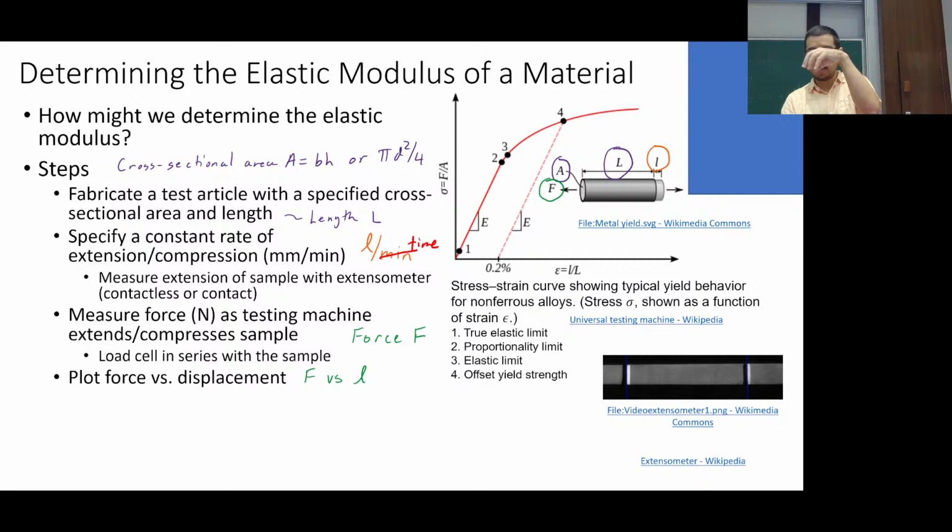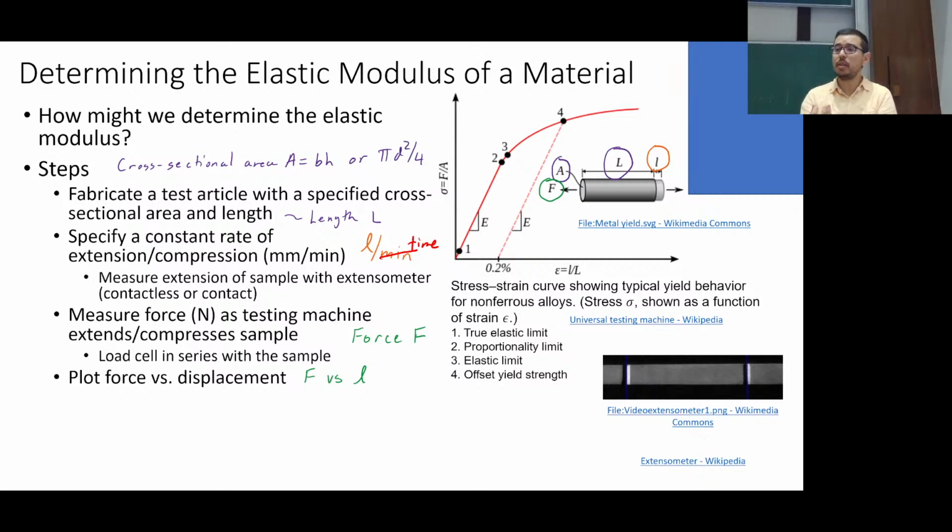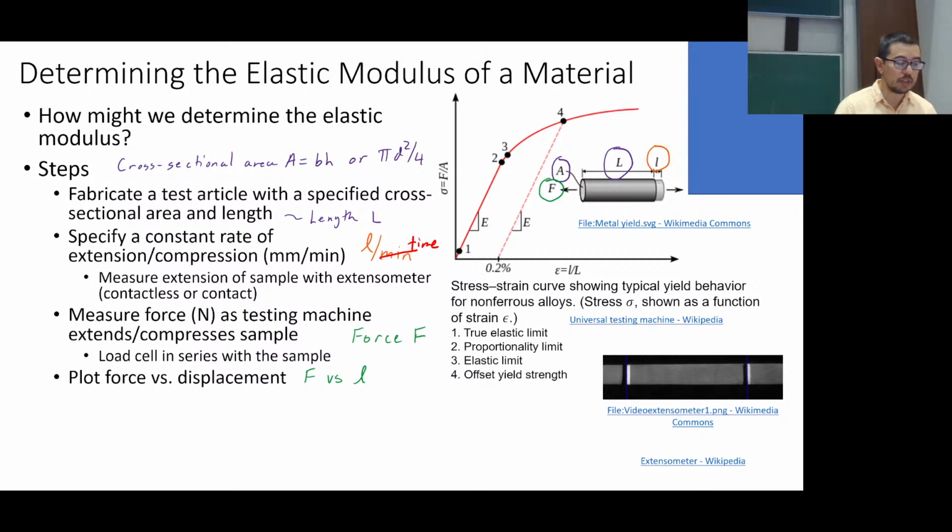So there's a head that's going to be moving, and then there's a base. Knowing that it has some gear ratios, it probably has an optical encoder somewhere in there. I don't know exactly how they're doing it. But we're just using the displacement of the head relative to the bottom, and that seems to give us good enough results. And then there's a load cell. The load cell is sitting on the bottom in our case, and the load cell also has some compliance in it because it's pretty hard to magically measure force without having some type of displacement associated with it. Of course that stiffness has to be pretty high so as not to affect our system.